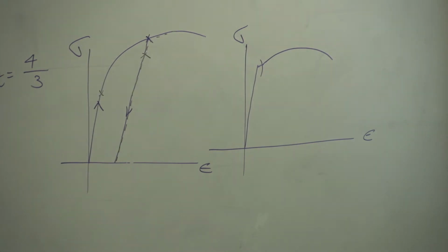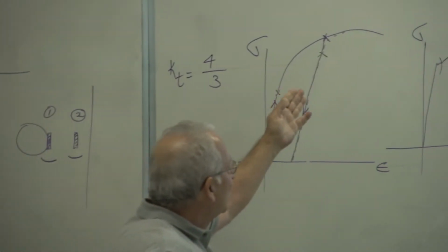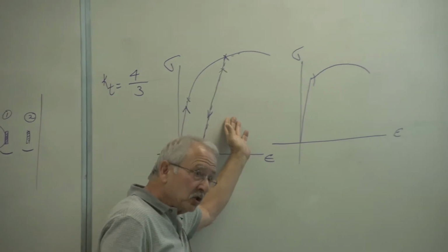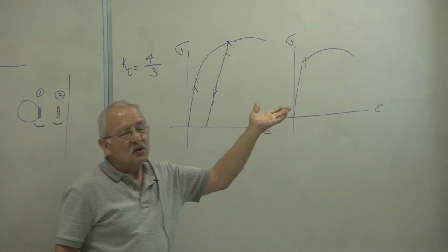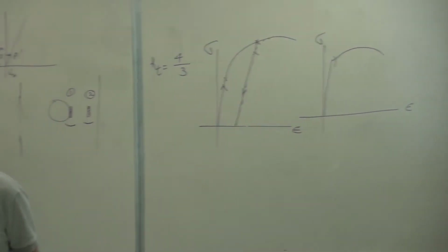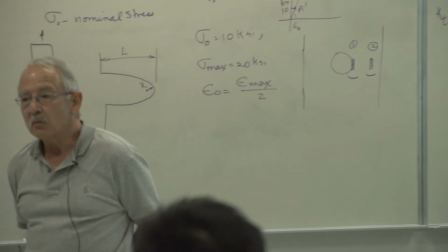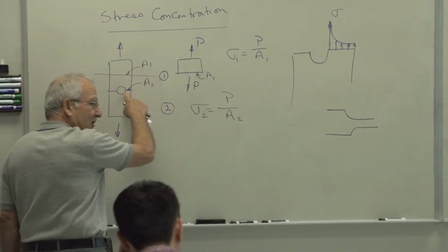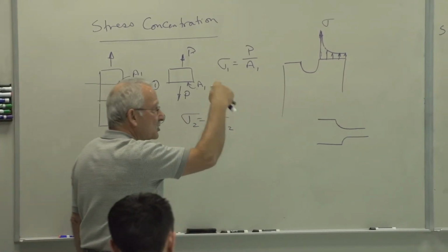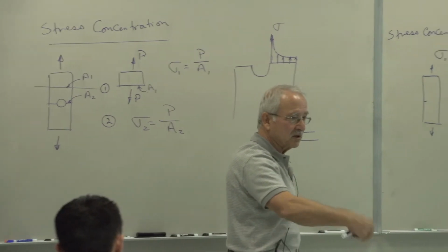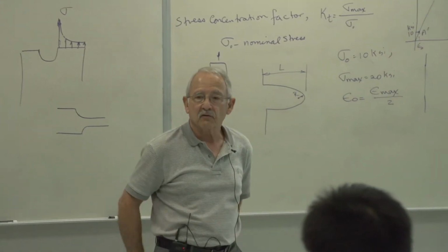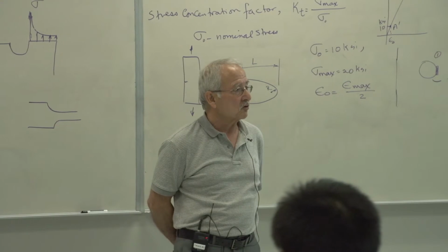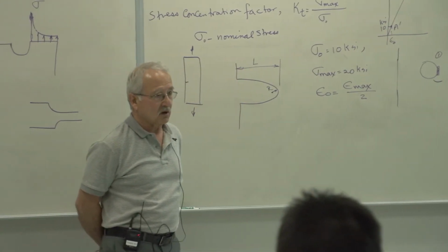So, the stress concentration factor has decreased. The strength of the material has increased. So sometimes we don't even use the stress concentration factor. We say, number one, this is very localized, it's right next to this flaw. Number two, the stress concentration factor decreases. And number three, the material gets stronger and therefore can resist higher stresses. So we don't use the stress concentration factor.